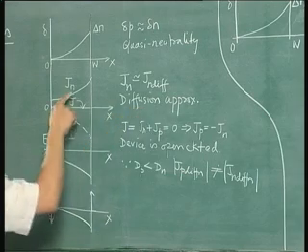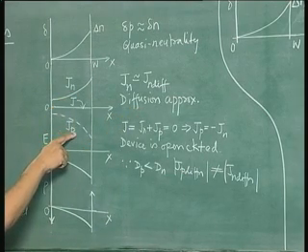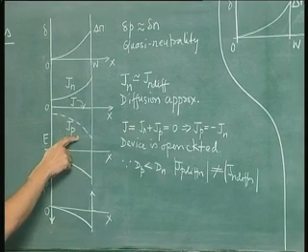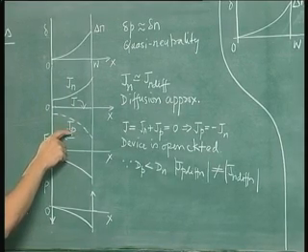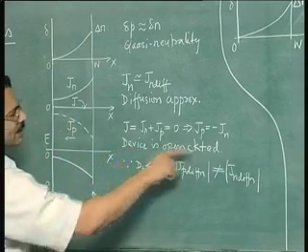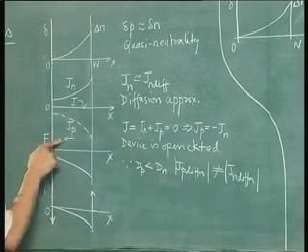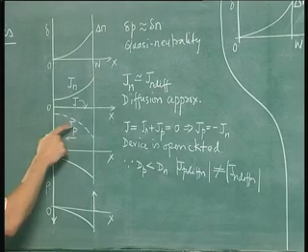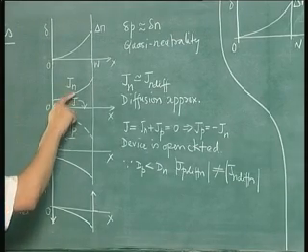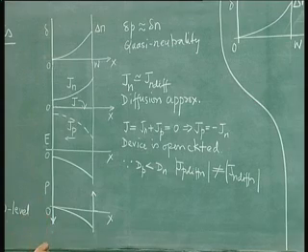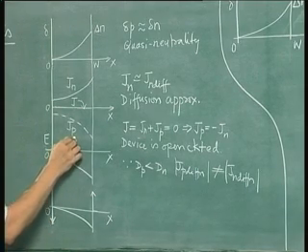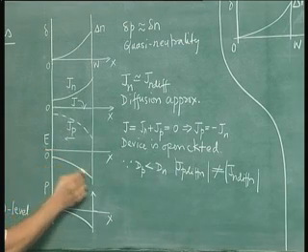We have already made the diffusion approximation, but the hole current is because of both drift and diffusion, and the drift of holes is such that it adds to the diffusion so as to make this current equal in magnitude to Jn, because that is a condition we should maintain when the device is open circuited. So that is the role of the electric field. It is to bring the hole current in step with the electron current, so as to maintain a total current J of 0 value. The electric field is in the negative x direction, that is why it is shown on the negative axis.